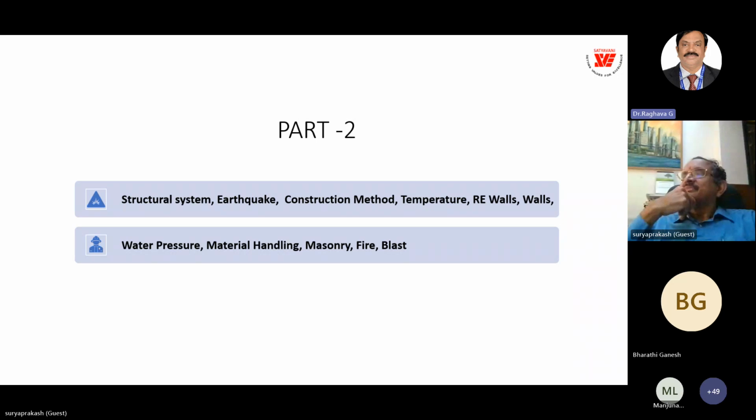And the third question, you mentioned about the problem of the excessive retarders used in the RMC. Correct. How was that problem solved? Actually, it's not the problem with the designer or the supervising engineer. Normally, what they do is they will give a tin of retarder to the truck driver, the transit mixer driver. They are non-technical, actually, and they try to dump the entire retarder in one go, so that they don't have to worry. They think, actually.